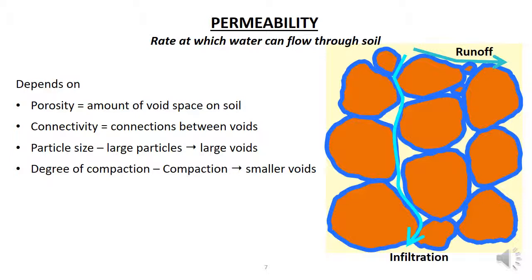Typically, 80 to 90% of rain falling on loose gravel will soak into the soil, with only 10 to 20% flowing over the surface. In other words, 80 to 90% becomes groundwater, while 10 to 20% becomes runoff. However, only 30 to 40% of rain falling on bare clay surface will infiltrate into it. The rest will flow over the surface, or it will pond if it cannot flow.